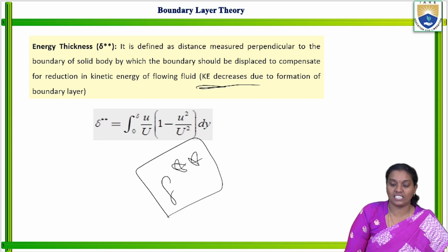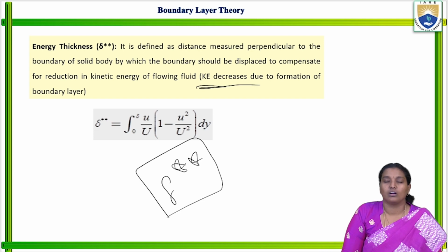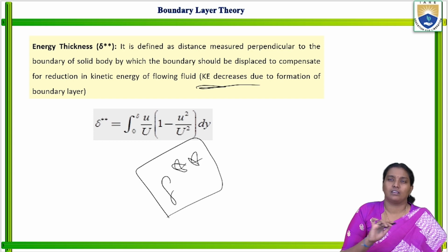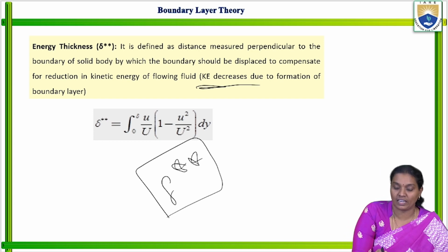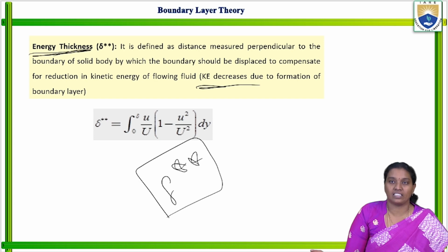To compensate for that, the displacement, measured as a distance perpendicular to the boundary of the solid body, is nothing but the energy thickness.